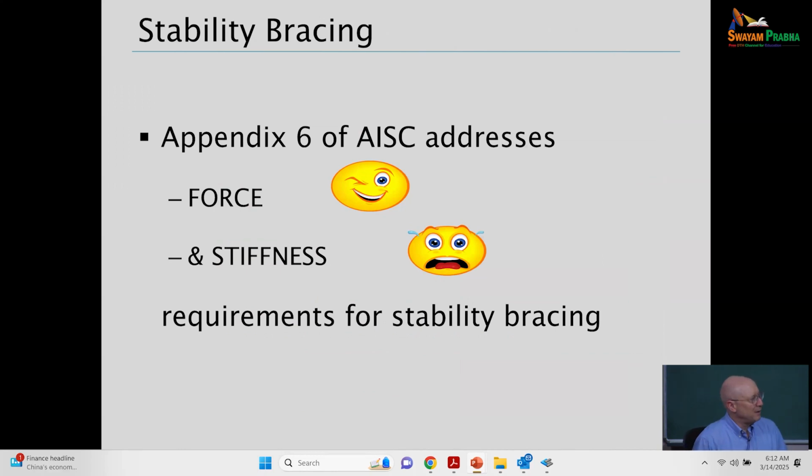All right, so traditionally, engineers would often handle column bracing simply by a rule of thumb, such as, oh, I need to design the members that are supporting the column out of plane for, say, 2% of the load in the column. We're going to find that the rules in Appendix 6 actually are relaxed relative to that. The force or strength requirement tends to be smaller than that.